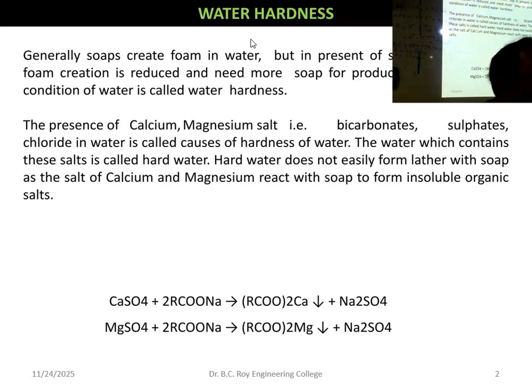And as a result, what happens? The scale is not uniform. Somewhere the scaling is thicker, somewhere thinner. There is a crack in the scaling. That is natural. So the hot water and cold water imbalance will produce a lot of stress in the boiler, and the boiler will crack. Got the idea or not? Inside the boiler you have a coating, suppose, some sort of salt deposition.